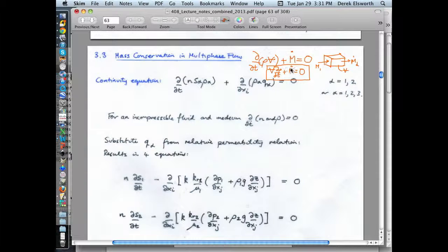So it says that if the amount going into the system is greater than the amount going out of the system, then we have to have a net accumulation. If the volume of this control volume doesn't change with time, the only way we can do that is by changing the density of it, by making it more dense because we're cramming more stuff in because nothing else is going out. And that was basically what that expression is.